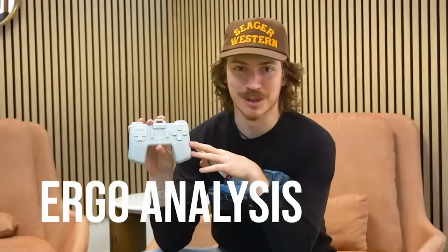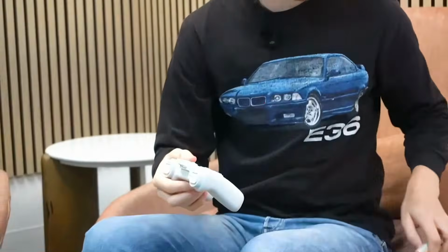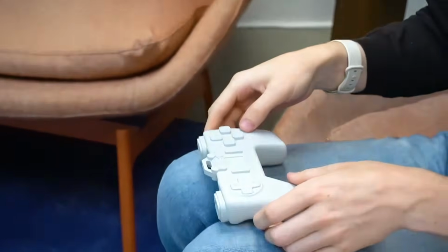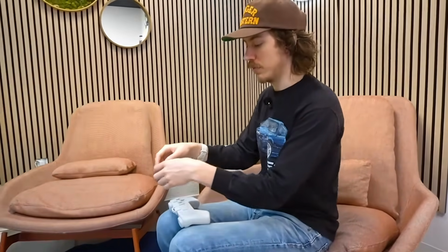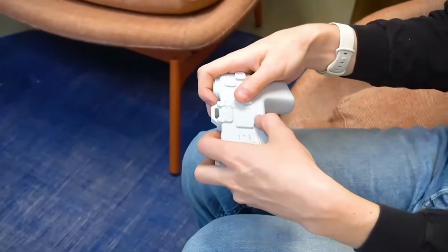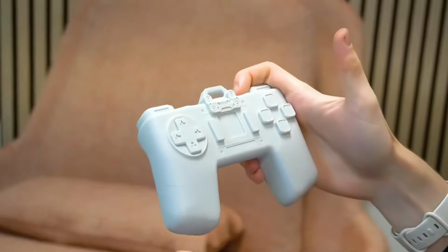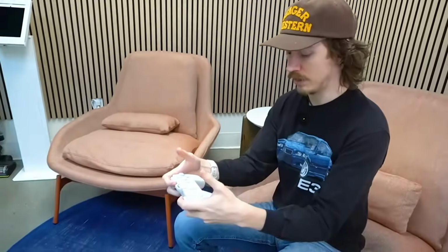We've got the controller printed out, and it took some liberties. There's some change in form, which is actually good. It went for something a little bit more ergonomic on the back. It's a little sharp, and it doesn't feel great in the hands, and let me show you why. When you are designing a controller, you want something to fit the natural state of your hands. Take, for example, if you were to really loosen up your arms and just set them down like this, you want it to fit within this grip. So let me show you what that grip is like. And you can see when I hold it here, we have a bunch of extra space here. So what ends up happening is that we're forced to put our palms in more and then our elbows tuck in.